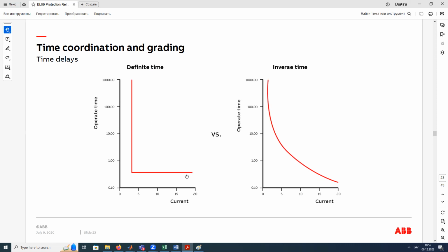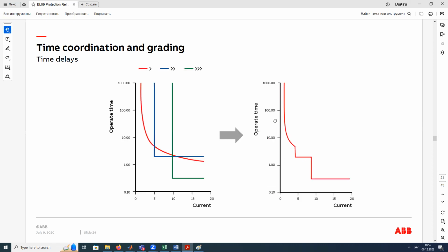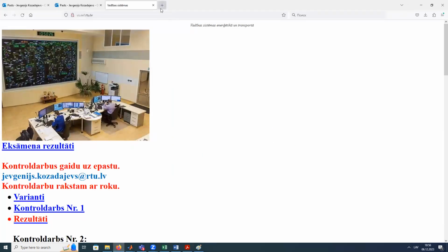When we have a protection device, mechanical, electromechanical, or digital, whatever, we get the input information about the current value and we make a decision to disconnect. And whatever the current will be, if it is higher than the set point, disconnect. And the inverse time for fuses is when the disconnection time, with copper melting and destroying, depends on the current value.